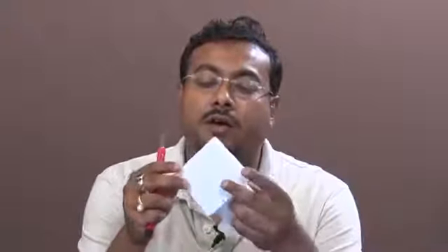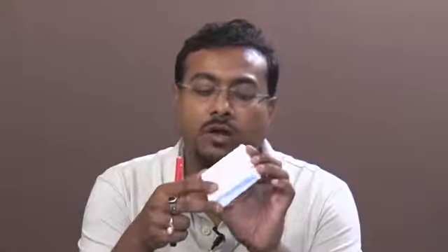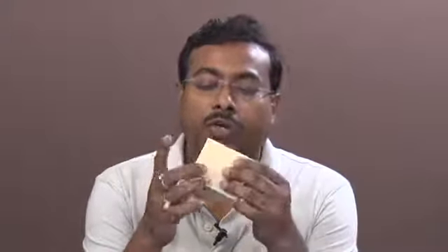You can cut it with cutters, you can sand it on sanders, you can get different kinds of shapes with thermocol. Next is low density. Low density thermocol you can just cut in straight lines or curved lines, but you cannot give organic form to this low density thermocol, because it is very soft. While sanding, the granules come out. Next is polyurethane. Polyurethane is a very useful material. You can use polyurethane with CNC milling. Within a closed chamber you can use polyurethane.